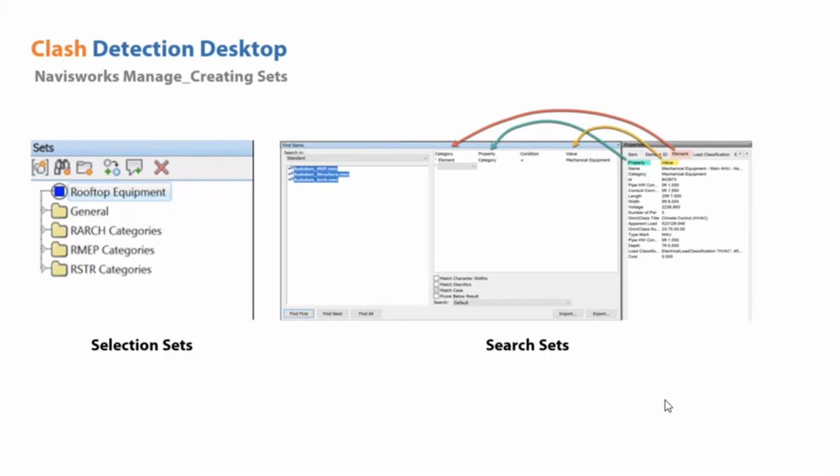The advantage of using a clash matrix is that in the clash matrix, we always define the model with specific clash priorities and clash groups. And these parameters, or these values, can be added inside the model authoring software and embedded as information for any of the model elements used inside the project. The advantage of a search set is that we can create search sets based on certain conditions and formulas, like an element belonging to this specific clash priority should be considered as a priority A element. Like that, we can create specific sets, and they can be used as a template for any kind of project.